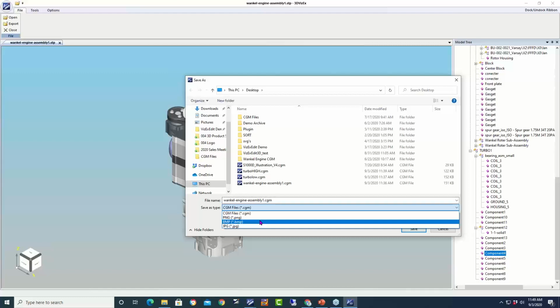Yeah, so the one thing I missed was we can save as image formats as well. So just in case you need a quick view of the shaded view, then we can always do that. Sorry, I missed that out. If you're alluding to, do we have our own 3D format, then no, we don't. So we reopen the STEP file or the IGES file. There isn't a way currently that we can save in a native kind of 3D format; we'd still have to open the IGES or the STEP file to work with the model again.